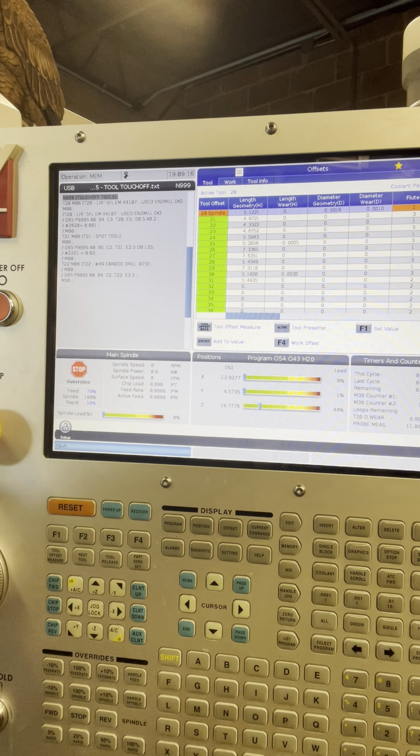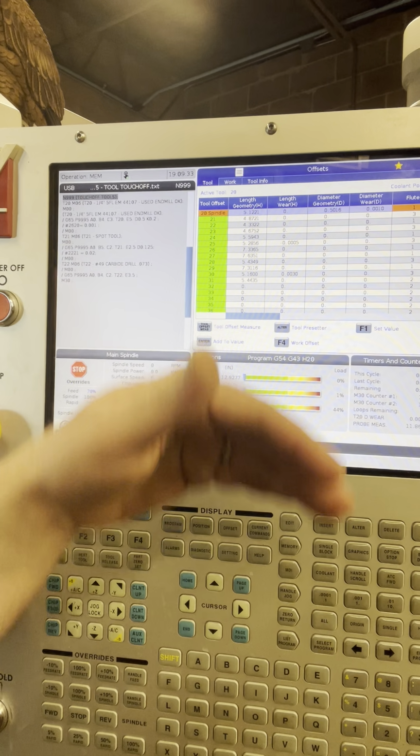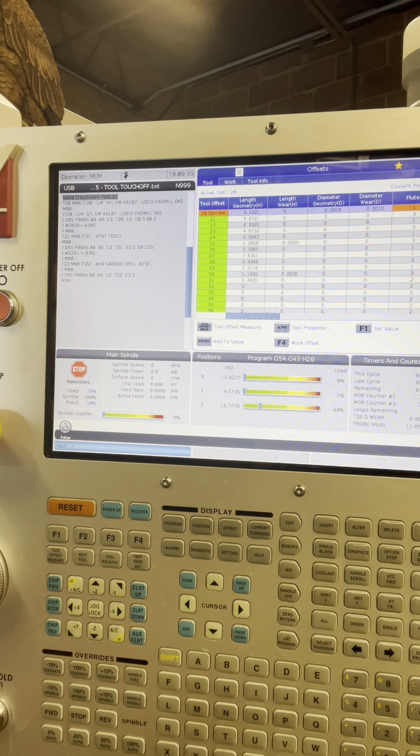But now, when you clear everything out, and what'd you say, 30 tools? Yeah, plus the probe, so 31 tools. So you're not setting the coolant for 31 tools. You may be adjusting it on a few of them or all of them. It makes it a lot easier for that. So that's another variable that we can push into here. But that one I did go into the Renishaw program and edit that.